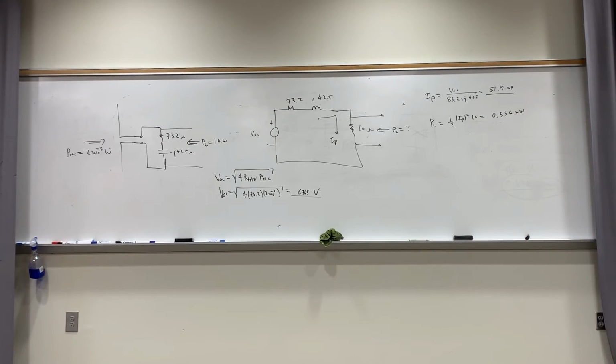To make sure you get the impedance right, you know how to find the fundamental frequency, the 1-0 mode, of a rectangular waveguide. The way you figure that out is that the longest dimension is a half wavelength, right? That half wavelength that you figure out will be associated with the cutoff frequency for the 1-0 mode. Remember this, class? So remember that.